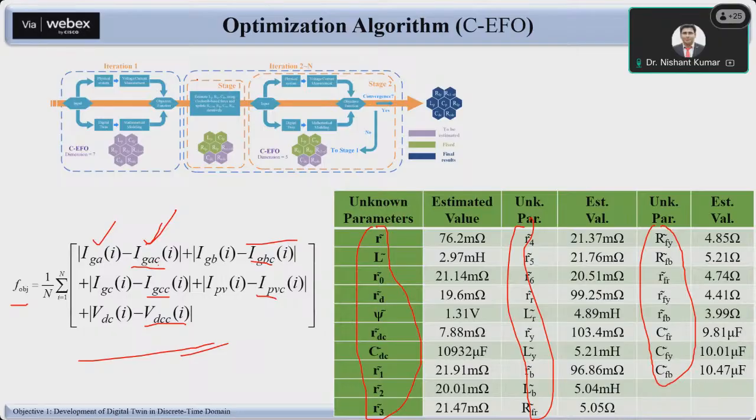But your switches, the DC-DC converter, is operating at 20 kilohertz, right? And then you are sampling at only 50 kilohertz. It means hardly 2 or 3 data points you are going to get in one switching cycle. That will not be sufficient to decide the behavior. So if you reduce this, then the transient performance will suffer. That's why you should play somewhere in between.